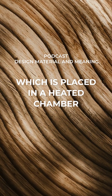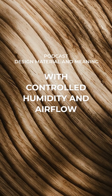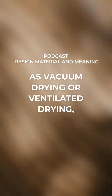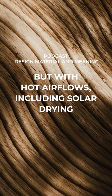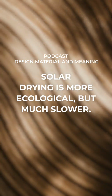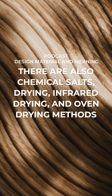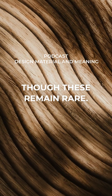Wood is placed in a heated chamber with controlled humidity and airflow, where moisture is removed using steam. Other methods also exist, such as vacuum drying or ventilated drying with hot air flows, including solar drying. Solar drying is more ecological but much slower. There are also chemical salt drying, infrared drying, and oven drying methods, though these remain rare.